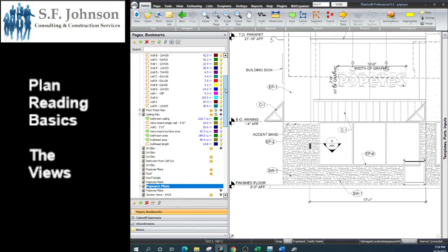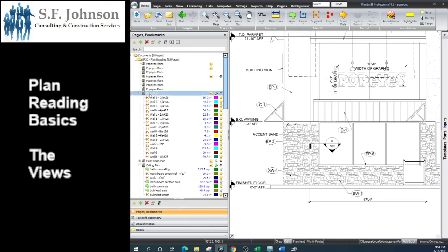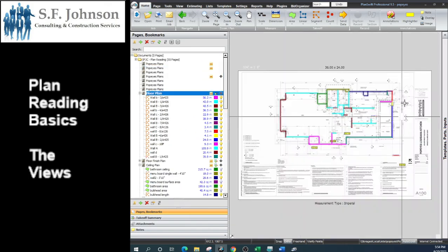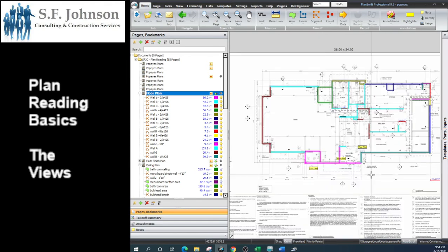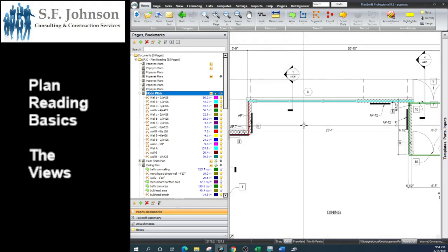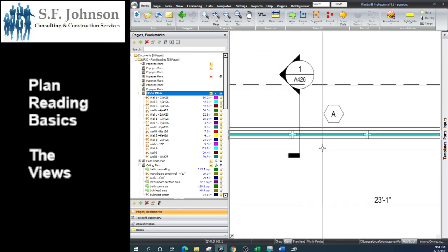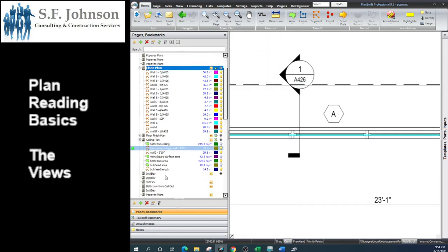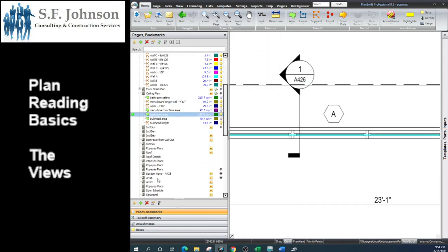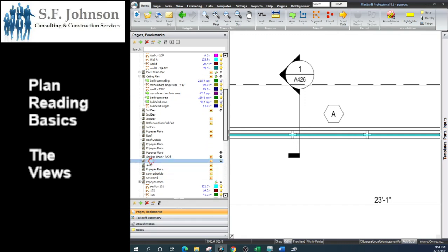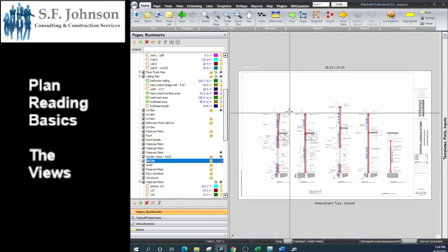You have the plan view, the most basic of the views from above. Right? It's the view from above, most basic of the views. What we see the most is the floor plan. From the floor plan, of course, we're measuring how many linear feet of wall, but we need a height for the wall. So the section view takes us to the height. Okay, so that's the second of the views, which is the section view. Okay, so the section view now gives us the height.